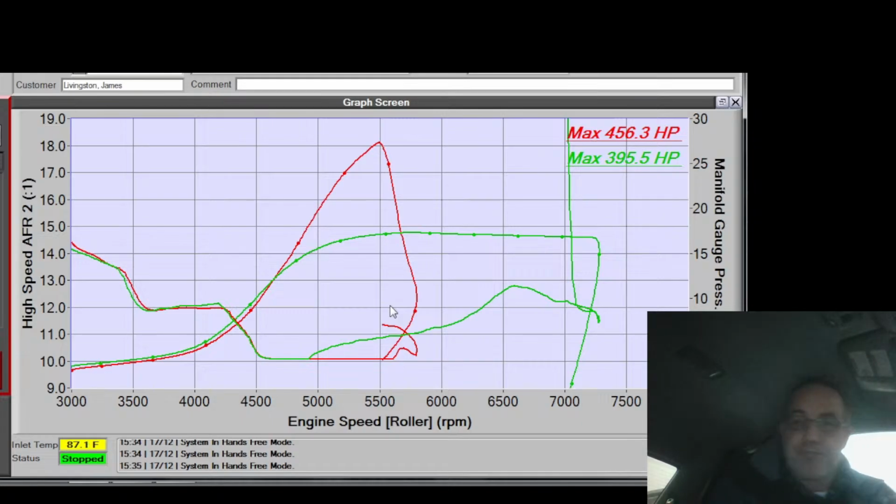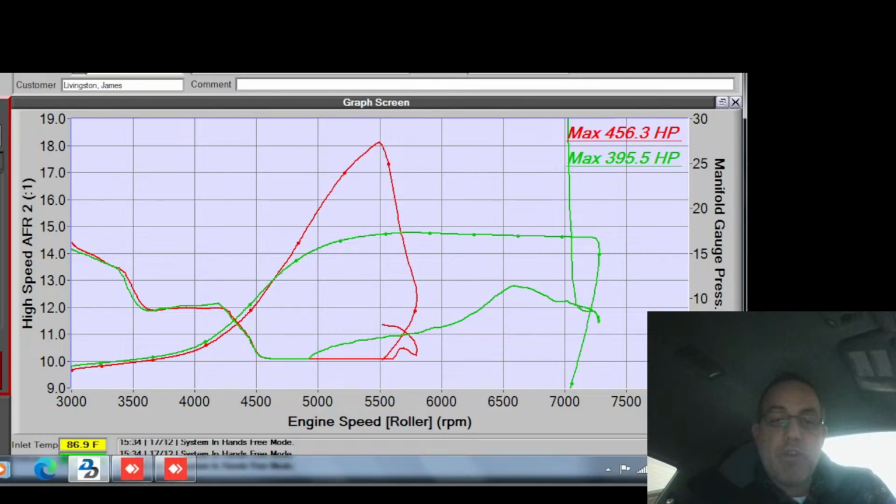I don't know. But anyways, this is a little laggier, but with this dyno, if I start the pull 5 miles an hour or a few miles an hour later, like say 35, the boost will come in like 500 RPM earlier. But I'm going to review my cam timing and see if that's tracking like it's supposed to. Okay, start the pull, cam timing. Oh, it's up there. It's 30 degrees, and it holds 30 for a while. That could be too much. It might be too much. That's a possibility, but the cam timing otherwise looks good.